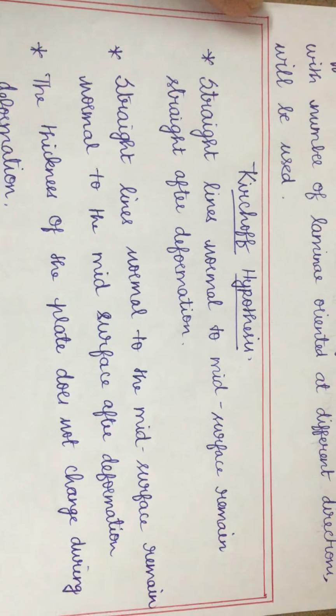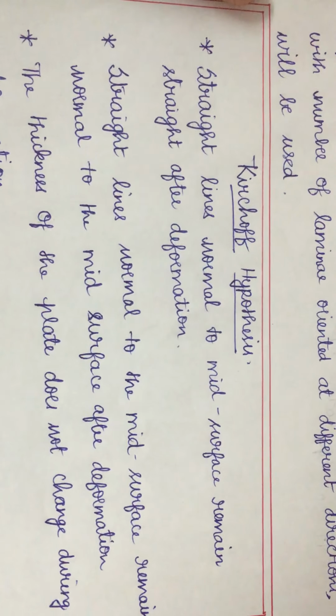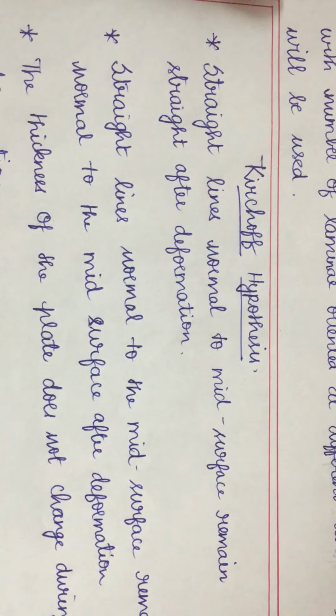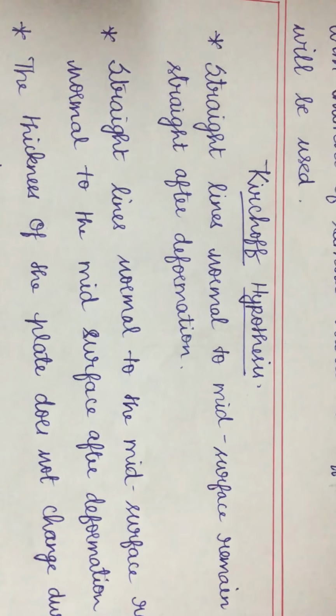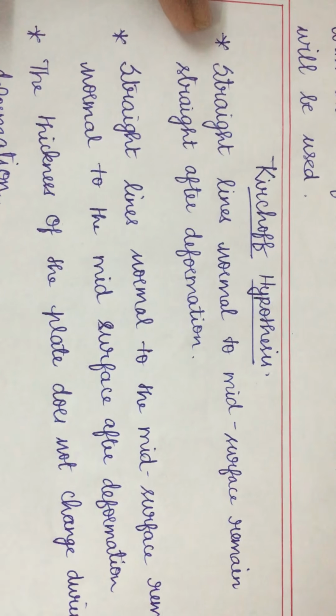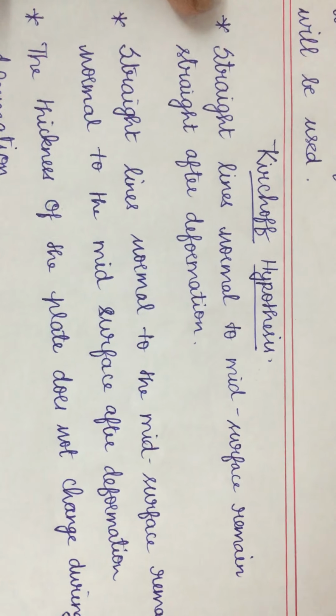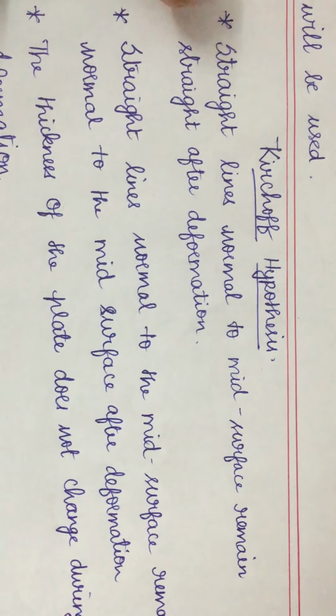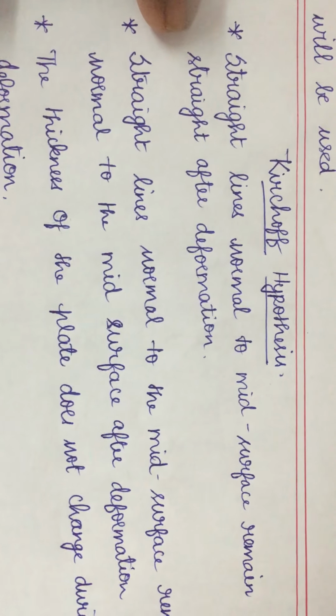Straight lines normal to the mid surface. Remember, if we want to solve a laminate, we will be having a mid plane. Straight lines normal to the mid surface remain straight after deformation.